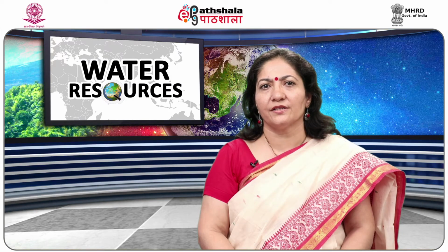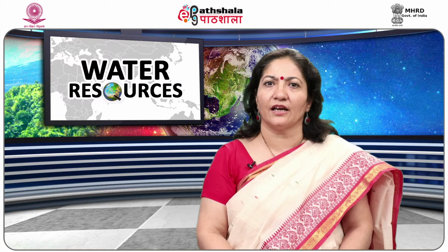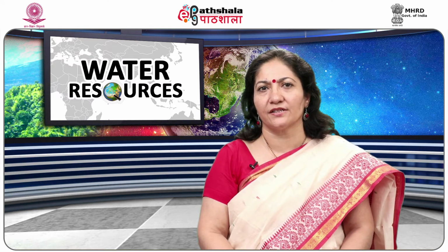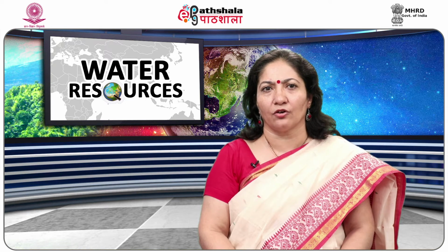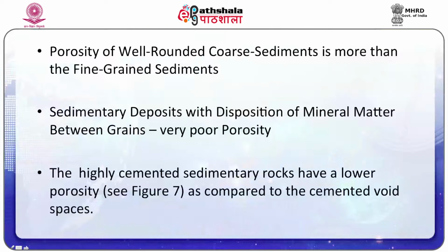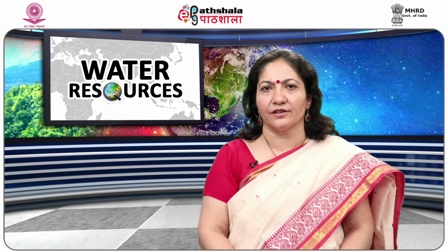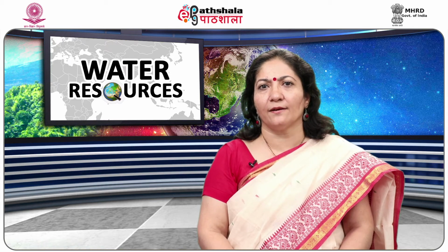The porosity of sediments is affected by the shape of the grains. They can be of various shapes like rods, discs or books. The fabric or orientation of the particles, if they are not spheres, also influences porosity, as depicted in figure 6, which shows the porosity of well-rounded coarse sediments, which is more than the fine-grained sediments. Figure 7 shows the sedimentary deposits with deposition of mineral matter between grains, showing very poor porosity.